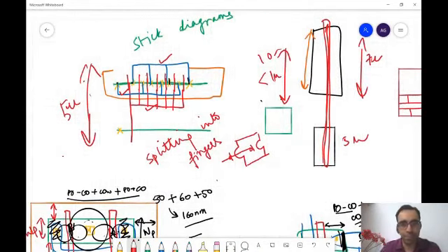Yeah. So this above stick, the top stick, this is one entire active region, which gets split into source and drain depending on where the poly is. Okay, sir. So let us call the first source and drain for transistor 1 and the next source and drain for the next one. Look, I put S over here. This is the source. This is the drain.